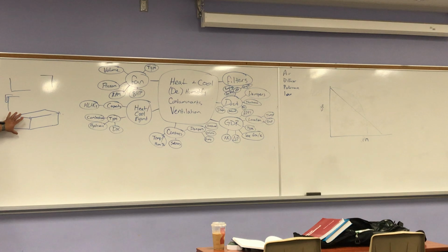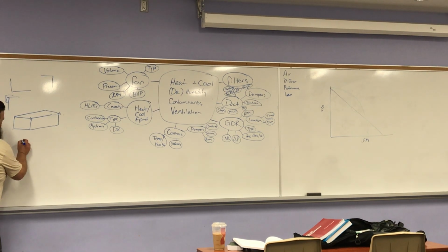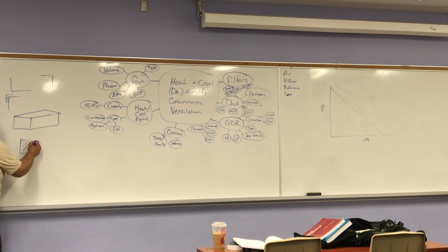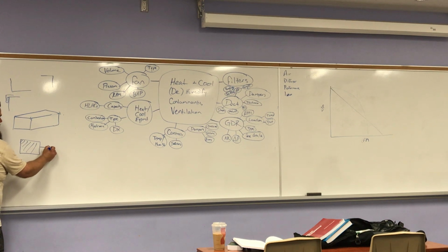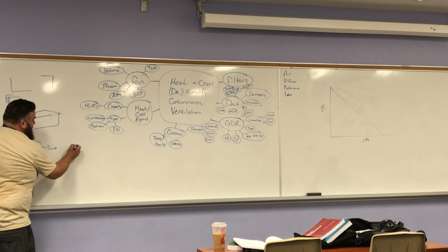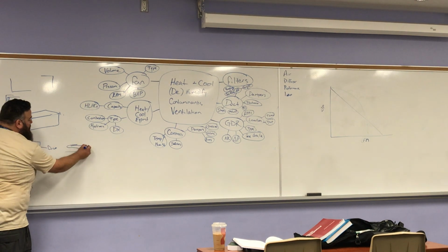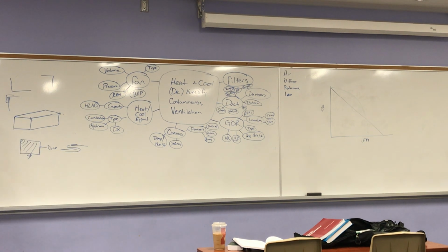The other thing is how the ducts typically connect together is called S and drive. If I'm looking at this on the face, you're going to have drive here on the sides and S here on the top and bottom. So the S is an S-shaped piece of metal. One tab of your duct, or one end, goes there, the other goes there.